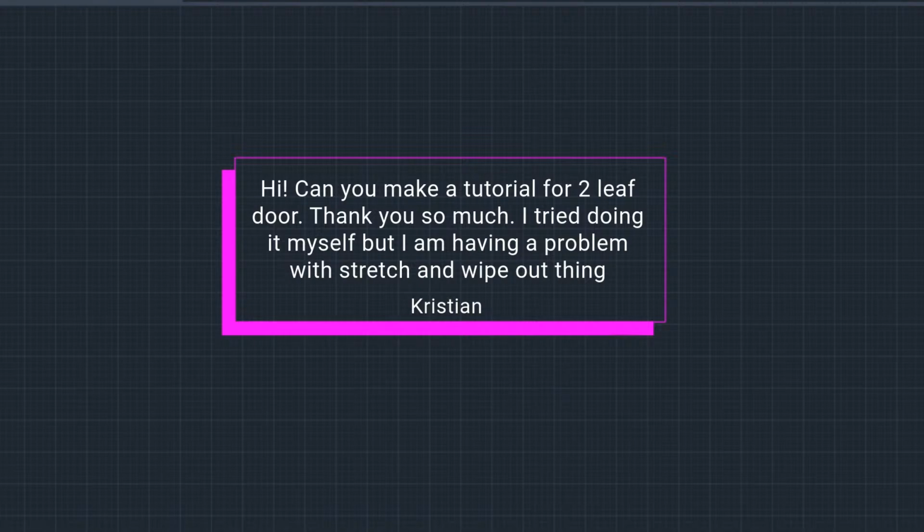So the way I'm gonna add it is following the instructions on my command line. I'm gonna select my linear parameter, I'm gonna select my point, which will be over here on the stretch grid, and then of course it's asking to select a corner of frame.